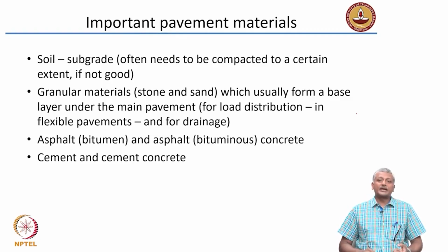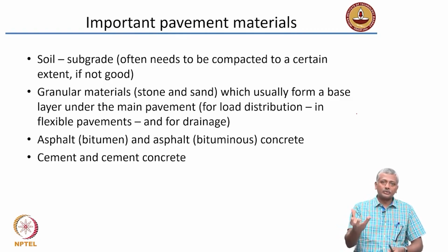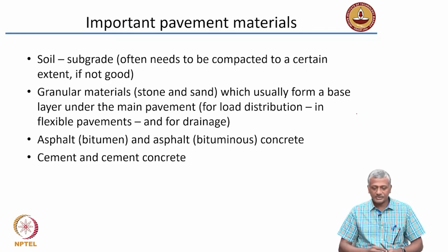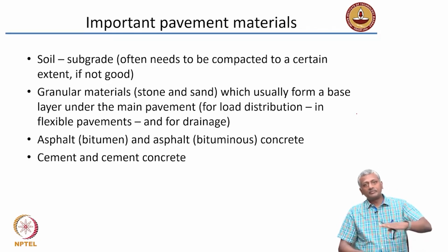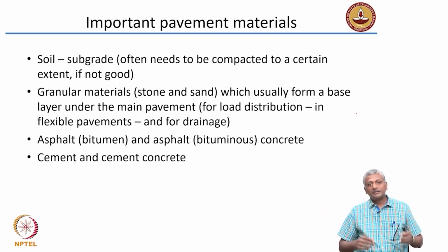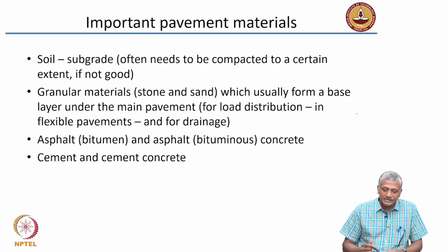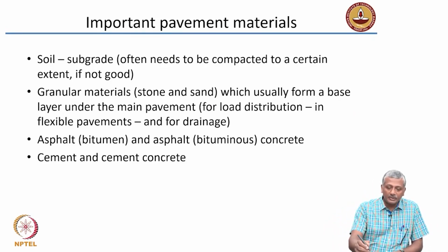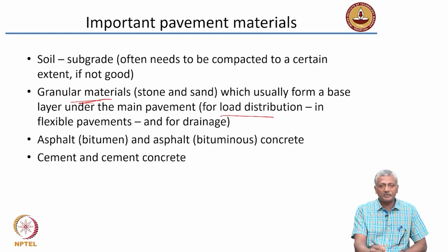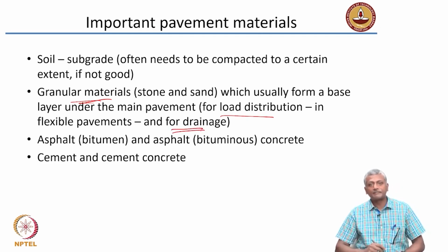Very often we choose granular materials, just stone, sand, coarse sand for instance, okay. They form a layer over the soil on which your entire pavement slab, either made of bituminous concrete or cement concrete, can rest, okay. And the provision of this granular material is useful not just for load distribution, which mainly happens in flexible pavements, but also for drainage.